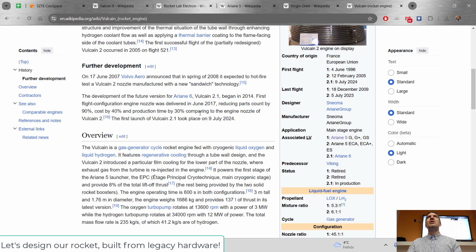And also in case of titanium, you can save sometimes half of the necessary material compared to the usual manufacturing methods. And titanium is not just expensive, but if you are doing anything with titanium, you also have to use titanium equipment to handle it, because otherwise the steel or iron and copper and other metals will diffuse into your finished product, and this will make it brittle, so it will break more easily.